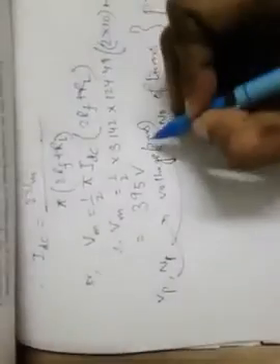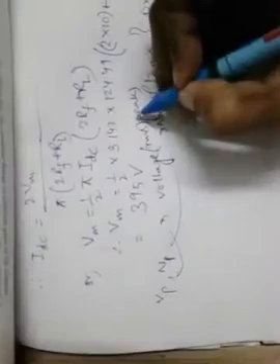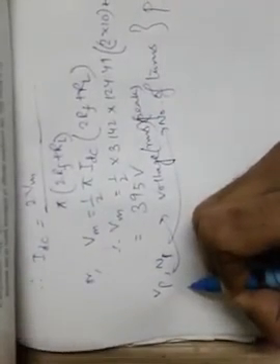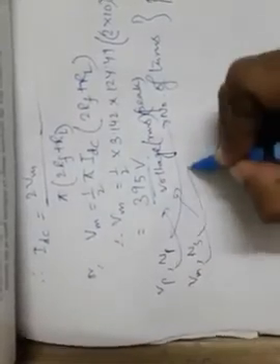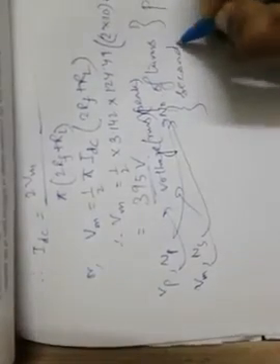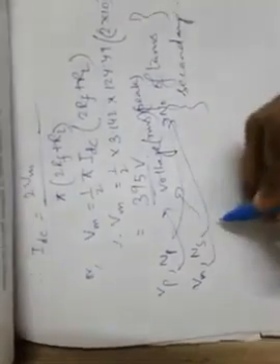This Vp is the RMS voltage, and Vs is the peak secondary voltage we have already calculated, 395 volt, that is Vm, and Ns is the number of turns for the secondary side of the transformer. So we can write